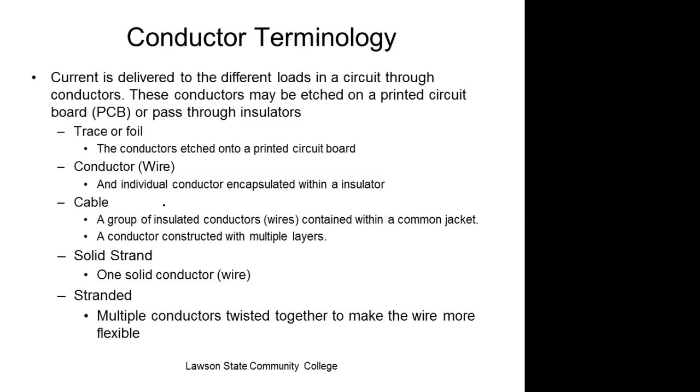So we have printed circuit boards. The conductors on the printed circuit board, we call these traces. And usually the traces are copper. The exposed part, they use a lot of tin right now. Tin has a very low oxidation rate. And they use a lot of tin to plate because, number one, it gets along real well with solder, and number two, tin is a lot cheaper. And usually by the time these things start oxidizing on these computers, they're already out of date anyway, right?